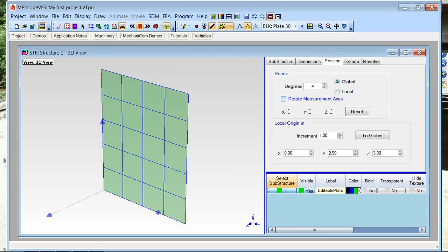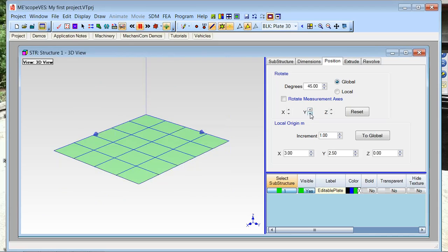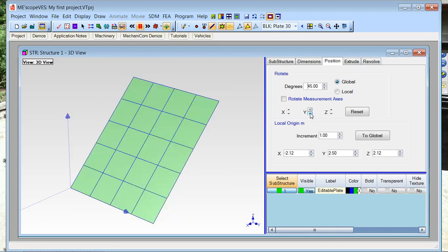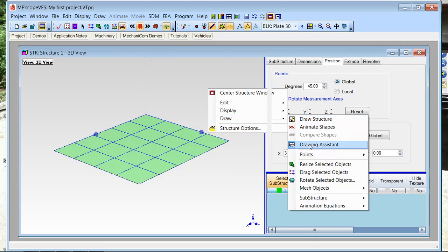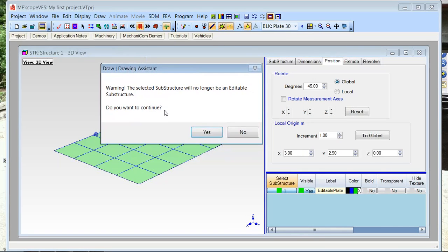And so this is where it's a good idea, before you take a lot of data on a structure, that you build the model first, number the points, and then use that model, or just copy it onto a clipboard and have a picture of it, print it out on your printer, so when you go to take the data, you know where these measurements are, what numbers they are. But I can't remember. I didn't keep good records. All I know is that I've got 30 measurements taken from points 1 through 30 in the z direction. So I've got them numbered here, and I'm done. What about the z direction?